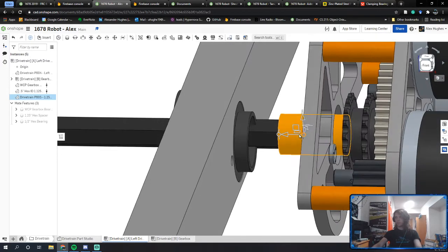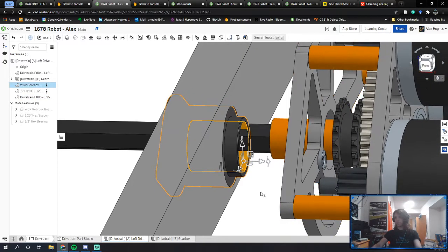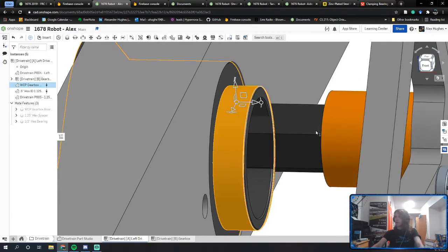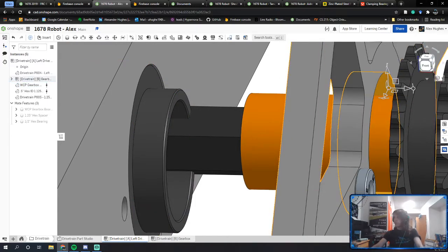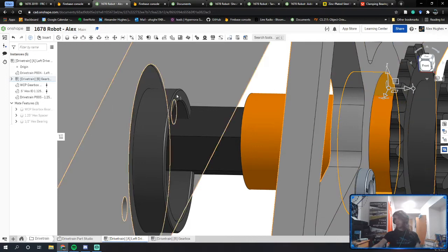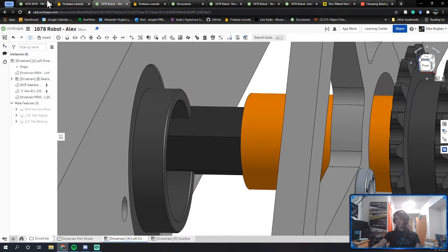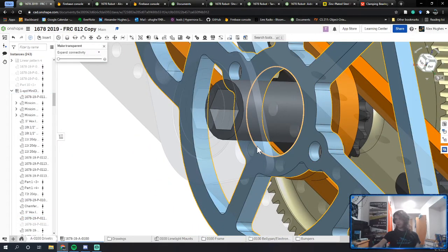Check something. Outer diameter of the bearing is 3/4 inch. The inner diameter is 0.973 or 937. Outer diameter is 1.123. Oh, so that's the issue. This hole here is actually too small for this guy. Is that messed up over here? I messed that up.